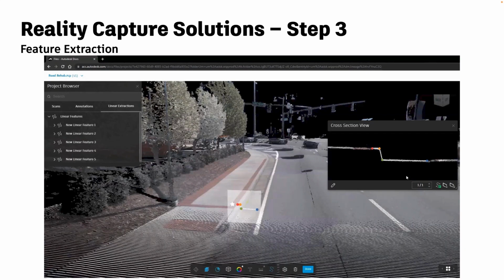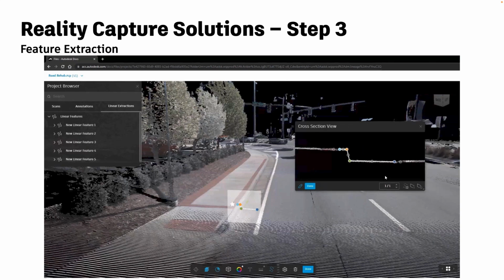I'm obviously playing here with matching the white line on the data, and I want to assign the feature code. So I specify, edit that, and I can specify exactly the feature code I want those vertices or those lines to have, because these are the lines we will be exporting and taking to Civil 3D. When it comes there, I don't want you or your civil engineers to struggle identifying what it is or colorizing, and I don't want them to spend too much time on it.